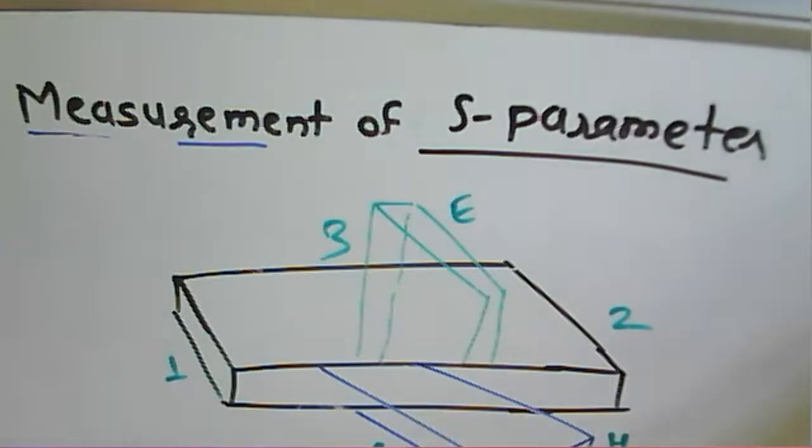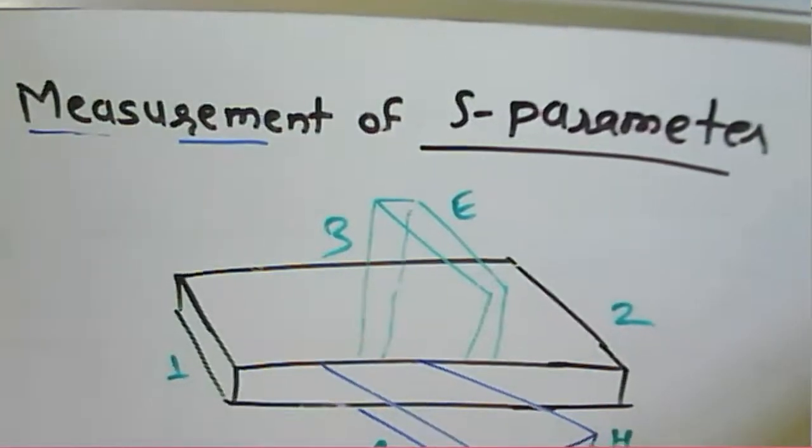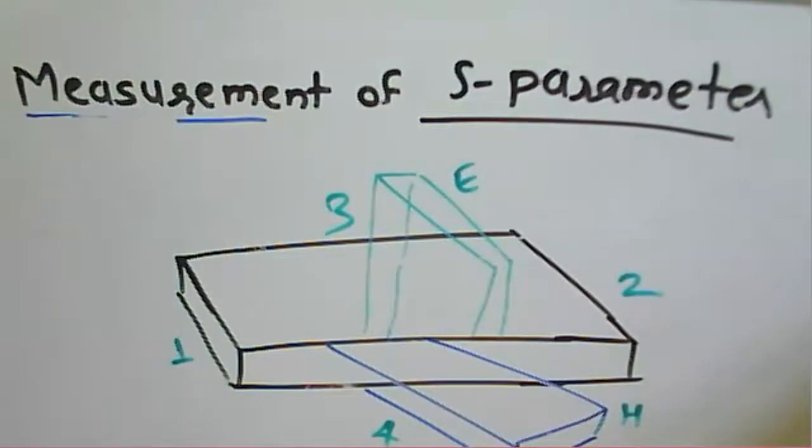For any component, we can measure the S parameter. If we want to find out the performance of any antenna, we need to know the S parameter of that given antenna, so that we can find out the isolation parameter, the impedance matching parameters, and all at a given particular port. Or impedance can be measured using the device.